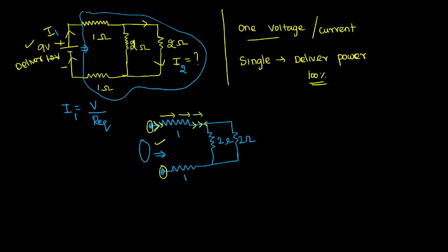See, after reaching this junction, what happens to the current? Definitely the current must divide into two. It divides into two, right? So, conclusion, if the current divides at a place, those two branches are connected in parallel. It may be 2 branches, 3 branches, it doesn't matter how many branches there are. From the point I observe, I am identifying this. Now does the current divide here? So, these two branches are connected in parallel.